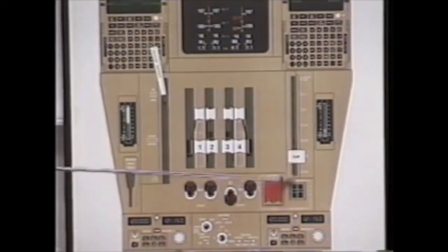Alternate stab trim switches. These switches simply are different wiring back to the control module. You must have hydraulic system 2 or 3 pressurized or the stab will not move. If you use these alternate trim switches, you can get a greater range of trim over the yoke switches. Use of the alternate trim switches will also not disengage an autopilot. If you use a yoke switch, it will disengage the autopilot.